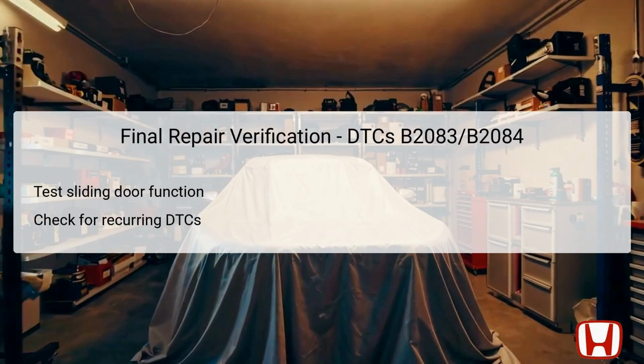Additionally, using the HDS to check for recurring DTCs will finalize the diagnostic process. If codes reappear, further investigations into circuit connections, components, and the power sliding door control unit may be required. Successful repair verification indicates that the malfunction has been resolved, ensuring the vehicle operates safely for the driver and passengers.